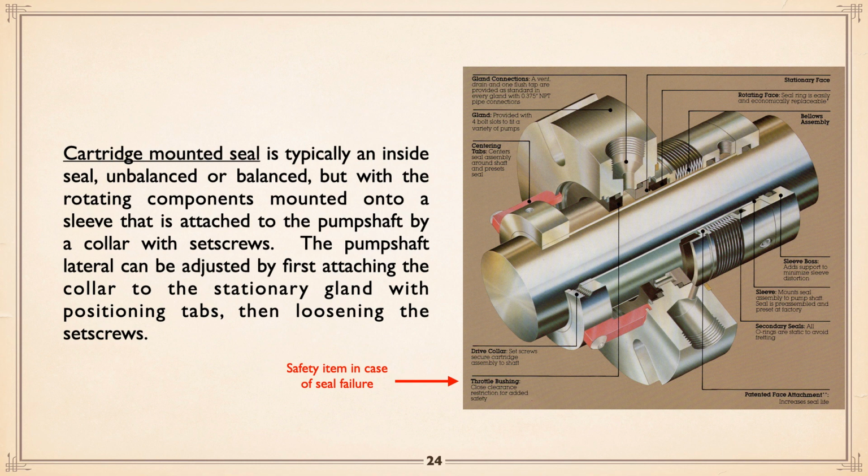So with this particular thing here, if you have to move the shaft, you put in these little red collar things which hold it. Then you can hold the outside part of the seal to the sleeve. Then you can undo the set screws, move the shaft. When you're happy with what you got, tighten up those set screws, and then remove those plastic pieces and put them on a shelf someplace, okay?